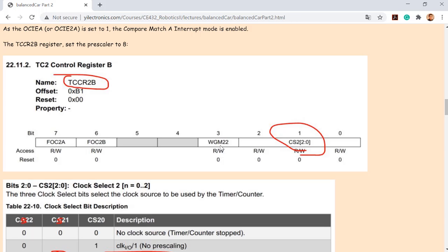Remember the RFID, your Sky card? There's no battery inside, right? No battery. It has a coil, so whenever you put it on the programmer, it's wirelessly charged, and a code will be sent, or the main device will program your Sky card after it's powered up by the coil. So definitely it depends on the programmer. I don't know the details of the code, but definitely the programmer can send a specific code to the card as a temporary ID, before it's being overridden.